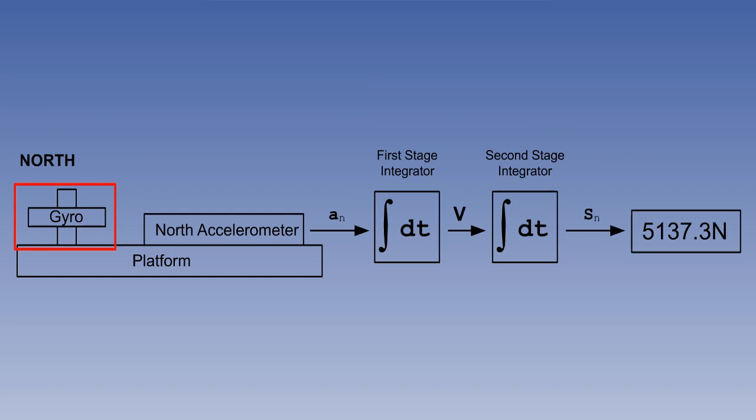Although there are 3 gyros and they are actually horizontal axis, we will diagrammatically show only one and we'll show it vertical axis to make it clear that its job is to keep the platform horizontal, just like an artificial horizon. The types of gyro used in INS can either be rate integrating gyros or 2 degree of freedom displacement gyros. Rate integrating gyros are widely used.